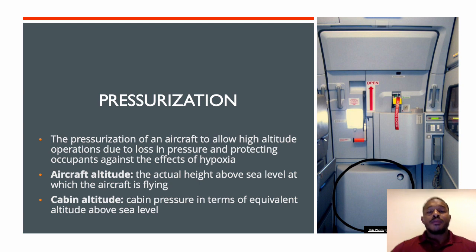Now, how cabin pressurization works is it uses the air from the engine, and then it takes that air, it compresses it, goes through the AC system, and it causes the air to set to a certain specific pressurization. Now, each pressurization is a little different, but they all have common mechanisms, such as using bleed air when we talk about aircraft.